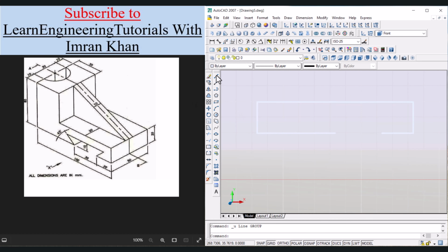Now here we will draw a line. So click on this line icon, click on this midpoint, and let's click over to, for example, 75. Enter. Press escape. Now click on line icon, click on this endpoint, and now click over this endpoint because it looks like a 45 angle. So click, press escape, press enter again, click on this line. Now move the cursor in this direction and look for 135 angle. Now this is 135 angle, click, press escape.